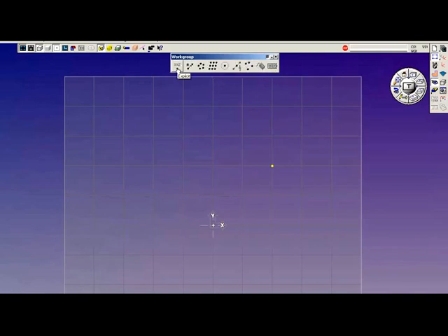Go back to the point tile, X, Y, Z, and let's put one at X minus 2, Y2. This time, we're going to use the multiple feature tile. By clicking on this tile, it generates the point and keeps the dialog window open, allowing me to continue inputting locations for additional points. For example, I'll type in minus 2 in the Y.